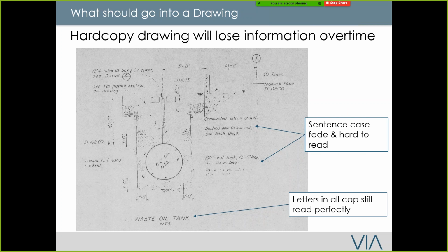As well, if you're not doing proper line weights, this is the problem you're going to get, because on site, contractors are going to just photocopy all the information. And you notice the drawing gets harder and harder to read. There's a reason why we want to make it as bold as possible. If you make your lines too light, let's say grayscale, those guys are going to have problems reading some of your drawings. So here's one example. I took a snapshot out of the old drawings. This is the problem with photocopies: you are going to lose information. So just be aware of that.